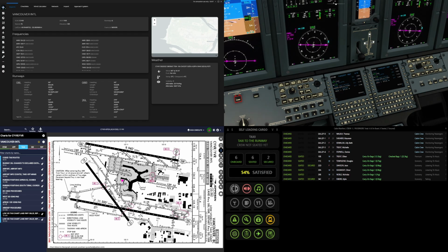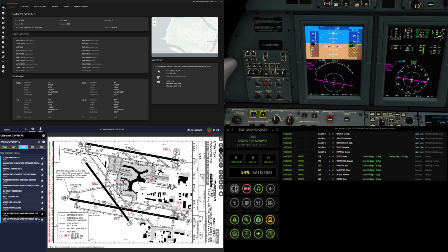Next page, takeoff weight, flaps are 15, anti-ice will be probably on during takeoff. And our V-speeds are here. Let's send them. You are hearing the boarding music at the background. Okay. So departure and arrival. Departure is 08 right, and it doesn't have any seats, so direct departure. And arrival, we will worry about that when we get close to our destination airport.